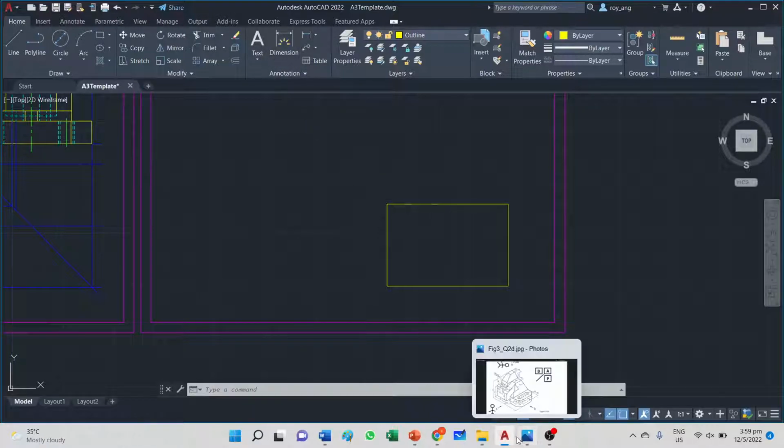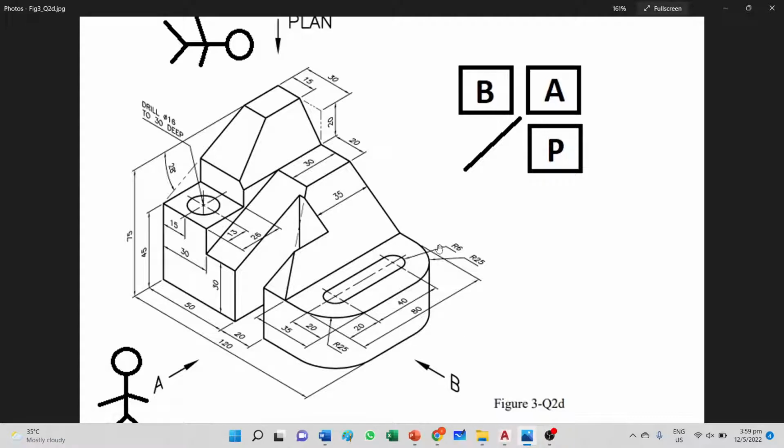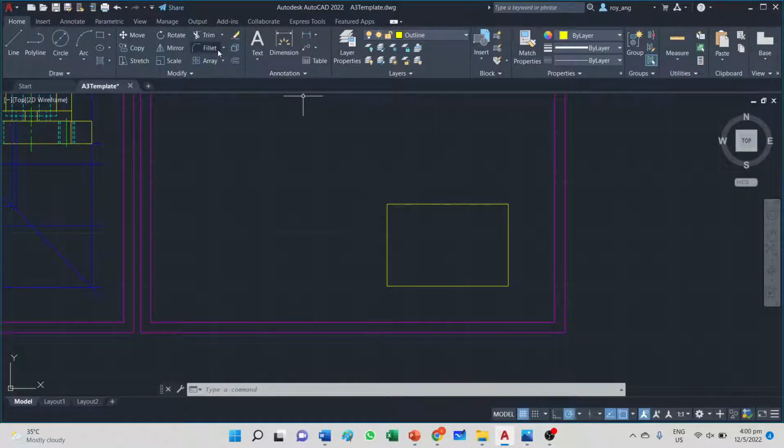The next thing that I want to look at is I want to draw this region here first, the fillet radius and the slot. Okay, we have to be careful that you do not presume the center of the slot is the same center as the radius. Okay, why and how do you know? Well, you have a rough feel about it because they have given you the dimensions of the slot position, and that tells you quite a lot of things, right? That the center of this is not the same center as the R25. So that is something that you need to take note of.